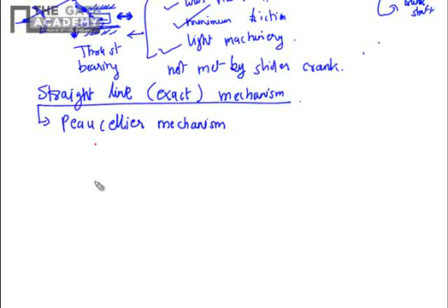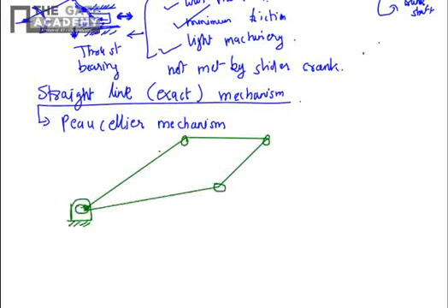So this mechanism is formed by a simple 4-bar chain which is isosceles also. That means the adjacent links are of equal length. So it is a kind of deltoid mechanism. Then in this chain you have an additional link. It is connected like this.